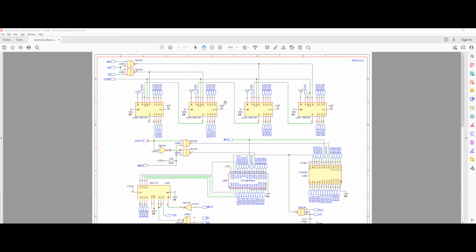However, there will be situations where we want to stay at the same step in our program counter, but we want our memory to jump to a specific address while the program counter stays on that step. Meaning that the program counter and memory address register are not necessarily always synced to each other in regard to the step that is executed.